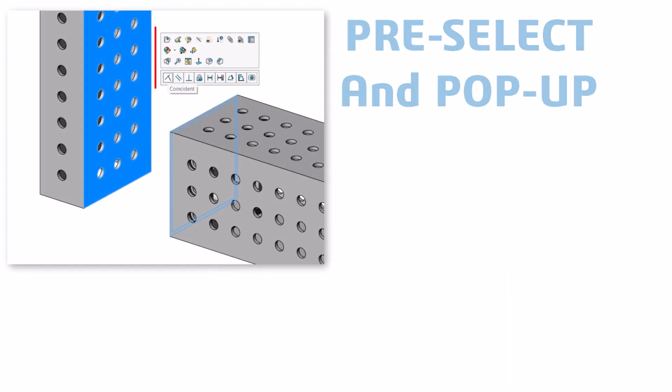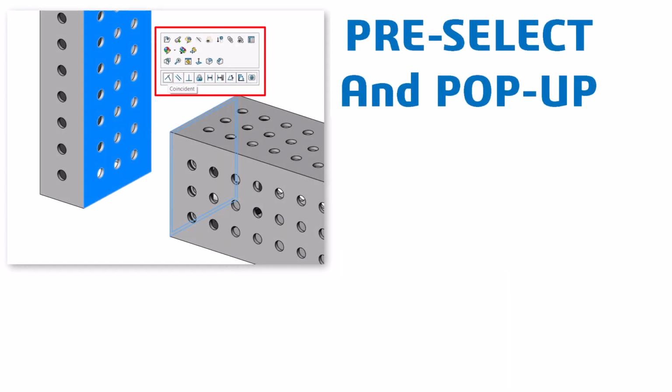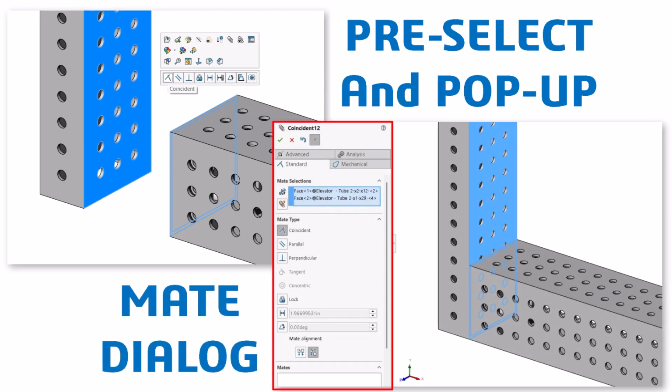My personal favorite, and the quickest, is to pre-select the entities and select the mate from a pop-up menu. Another way is to use the mate dialog. In this video we will take a look at both.